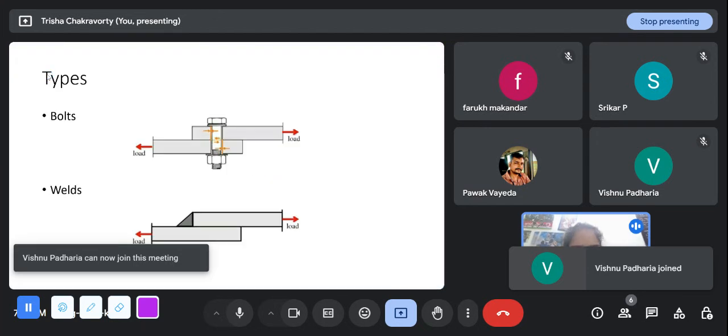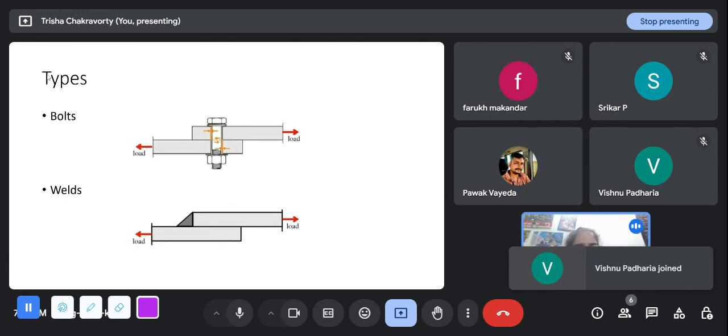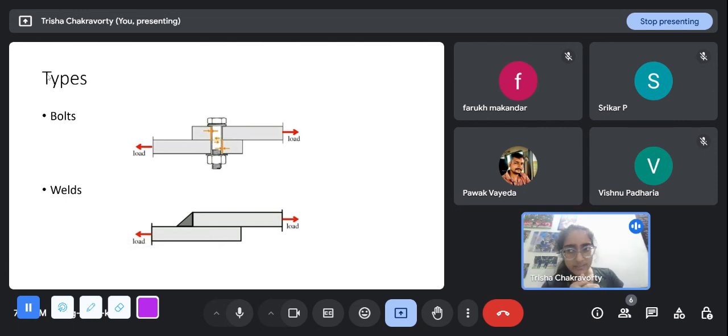Dynamic friction does exist even between two surfaces that have relative movement, but during design, since we simplify and want to work in the safer way, as soon as slip starts between the two surfaces, we do not consider the friction anymore, and we consider that the shearing and bearing of the bolt material is what is holding the structure together. So bolts develop their strength by three means.